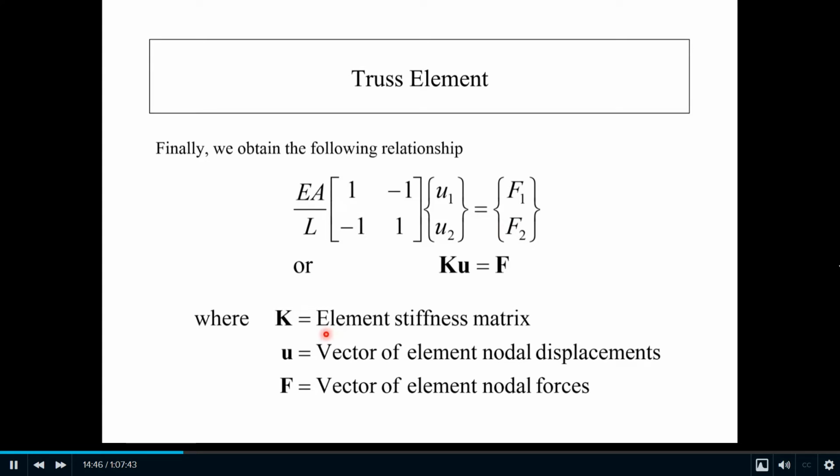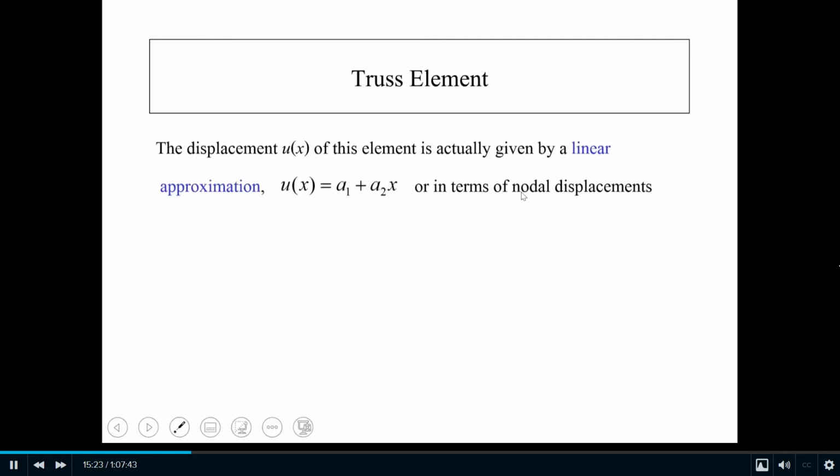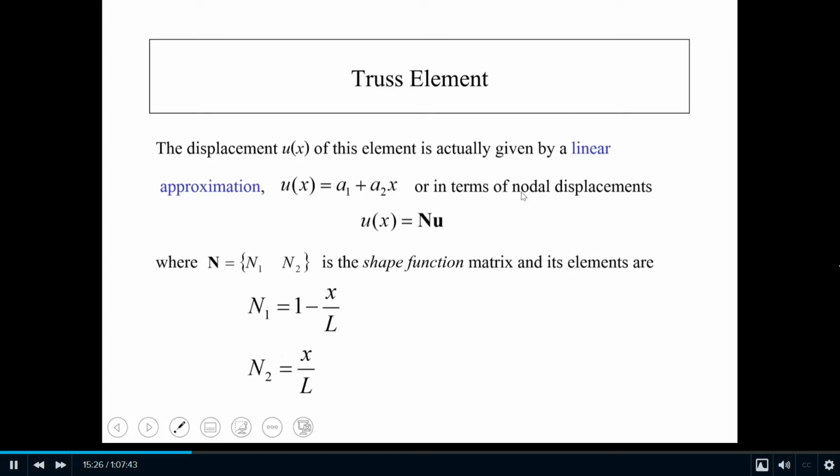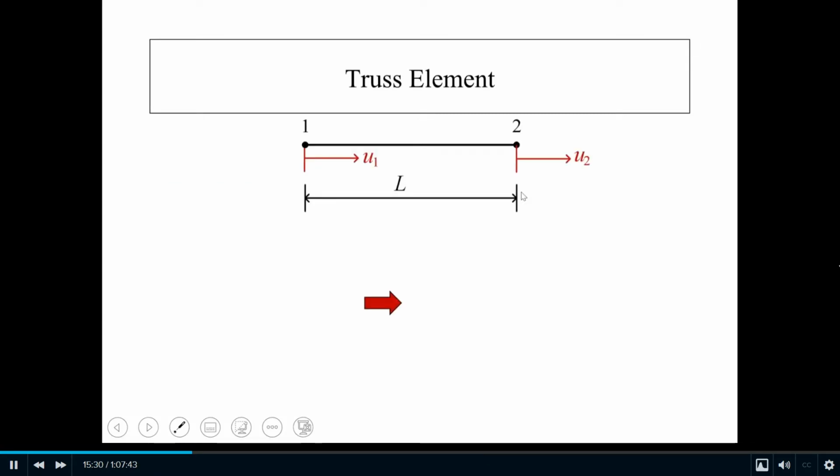So basically, what we need to derive is the element stiffness matrix for the beam element that relates here, which is not going to be U1, U2. Now it must be theta 1, W1 and theta 2, W2. And here it's not going to be axial force. It has to be moment and shear. Basically, I would say all of you must have seen that equation before when you studied structural analysis at undergrad level. But anyway, we will repeat this again, also within the context of finite element approximation.